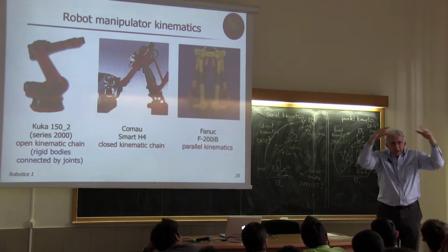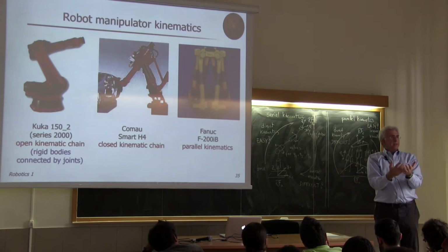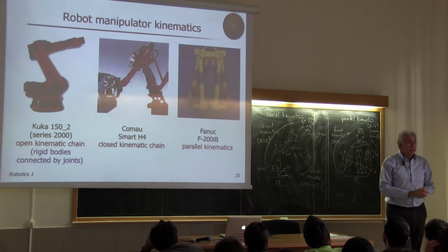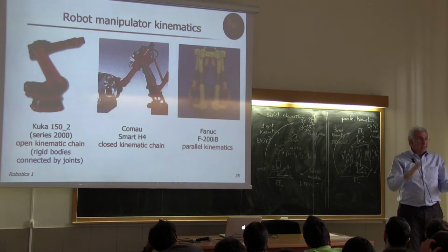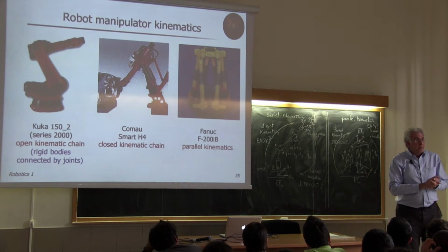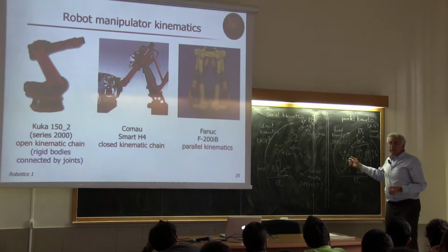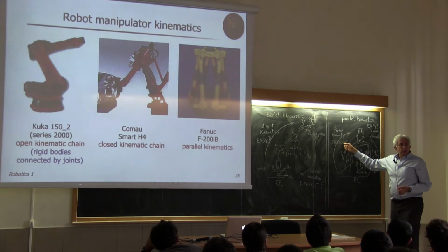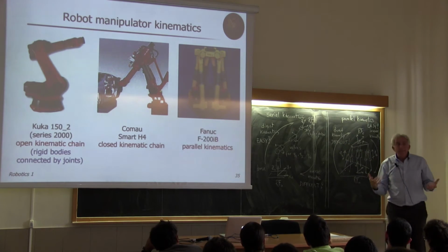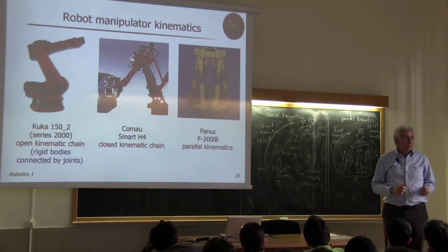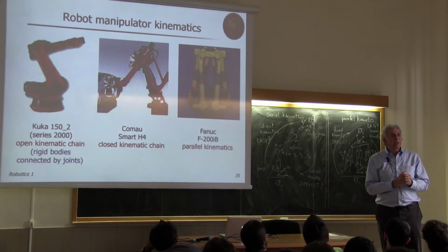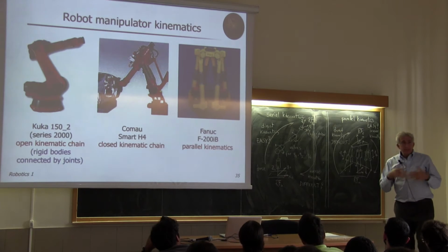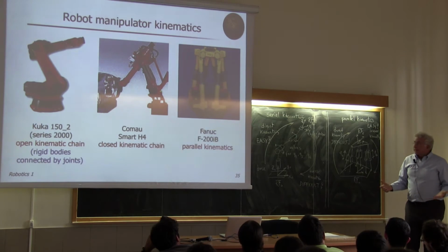So you have a kinematic constraint, which is of the form of a closed chain, in fact, but it's all closed. There is little serial or no serial at all in this structure. And so you may not even have a solution for the direct kinematic, and you may not even have a closed form solution. So it's exactly the reverse situation as for serial arm.